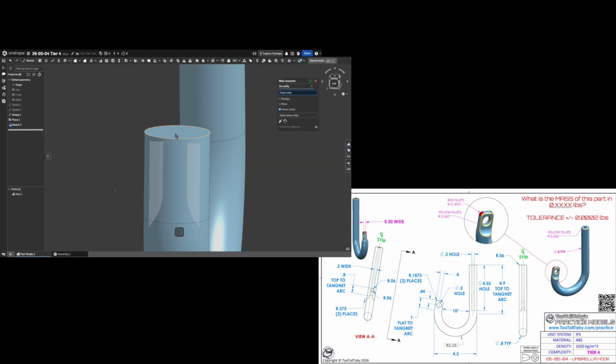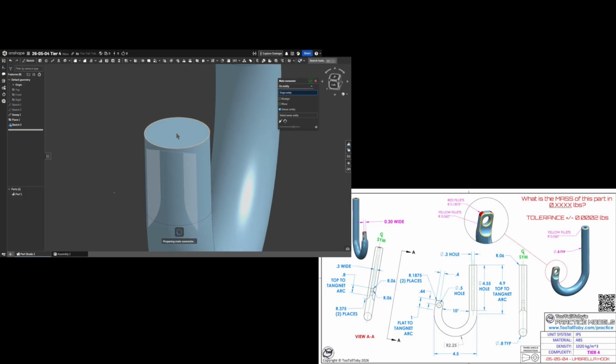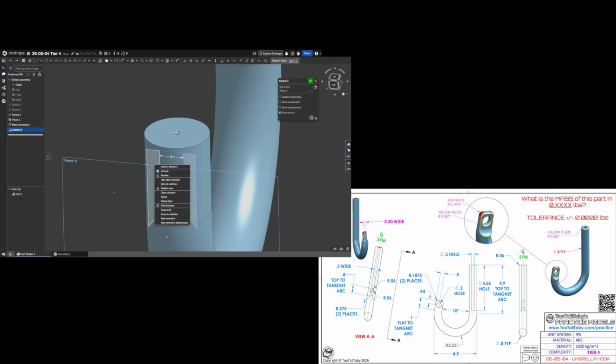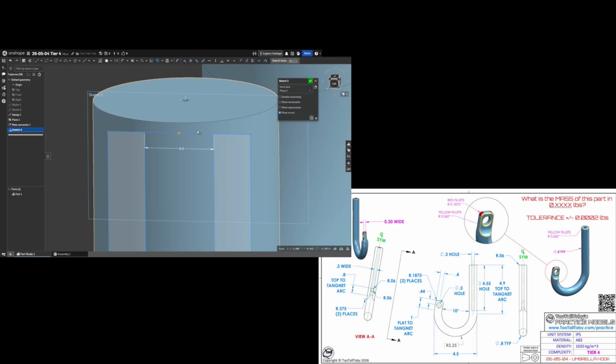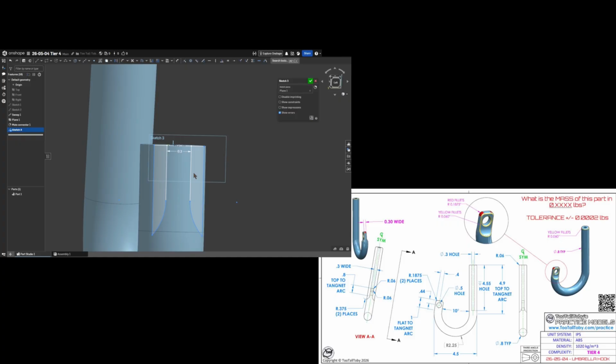We're going to put a make connector here. On shape. And now in this sketch, if we put it before the sketch, we can refer to that to find the center. Let's put that point in the middle of that. So now we can make this and that coincident. Nice.